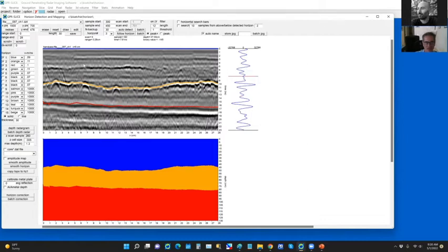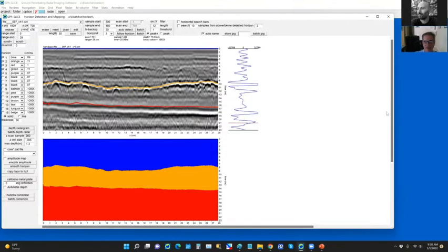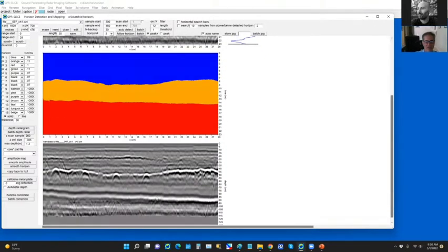If you have multiple velocities on different intervals or interval layering here, then this depth axis doesn't really mean anything. And you can't just put it in one location. You'd have to put it in all the locations because the horizons are variable. But we have what's called a depth radargram. And what that does is it adjusts the radargram to match the horizon thicknesses and the velocities. So if you hit depth. Okay. And if we go down here, so this is a radargram that's actually corrected from time into depth.